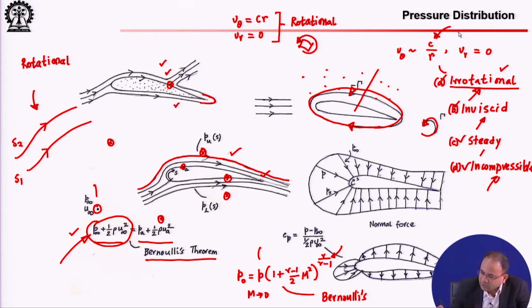On the other hand, you can show or see for yourself that here your fluid element will not exhibit a net angular velocity. It will try to rotate in one direction, but then there will be a rotation of the other axis. So, if you think of two mutually perpendicular axes, and we will show these things, you will see that one axis tries to rotate clockwise, the other wants to rotate anti-clockwise. So, overall there is no net rotation, whereas here both the axes would try to rotate in the same direction and your fluid element will rotate. So, that is the rotational flow.